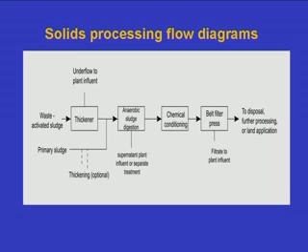Then it will be going to an anaerobic sludge digester, and whatever supernatant is coming will be separated and sent for further treatment. Whatever sludge is coming from the anaerobic digester usually undergoes chemical conditioning if we are going for a belt filter press for the dewatering, because chemical conditioning is required. When we discuss the belt filter in detail, we will know why this chemical conditioning is required. Once the dewatering is completed, it can go for disposal or for further processing or land application. So, this is one of the methods we can adopt for handling the sludge from an activated sludge process.